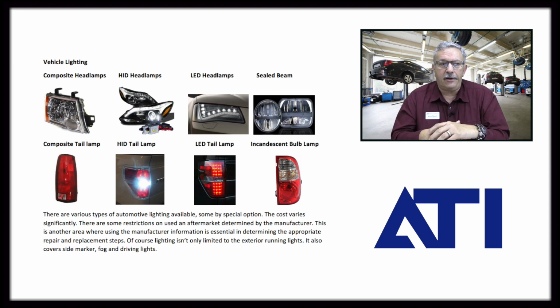So what do I look for? Well, if I just receive the part and I take it out of the box and I see condensation, I'm probably not going to want to use that part. Especially if there are integrated electronics bolted to it, because that gives me a question as to where was it stored, where did it come from, and could it have been in, let's say, a flood damaged vehicle. So just be very observant, as we're being told to order parts in some cases, of where those parts are coming from and the condition of the parts when they arrive.